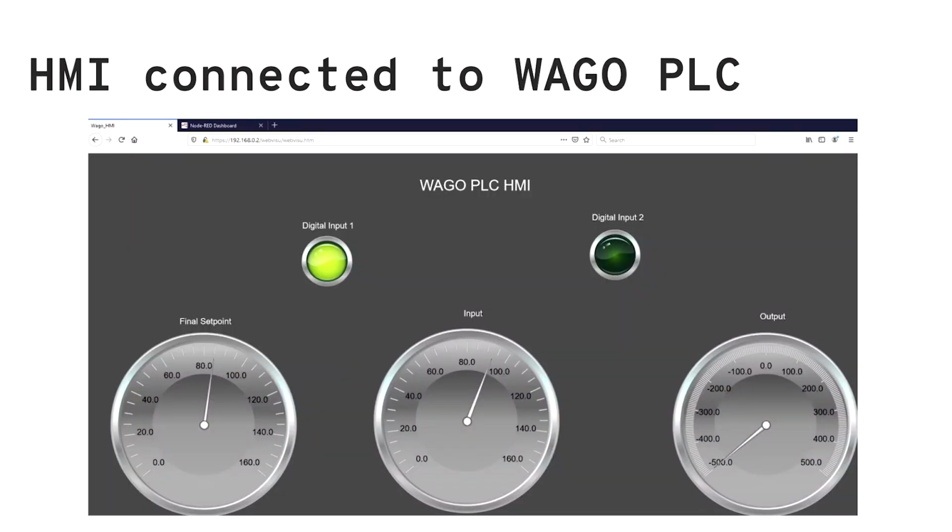And once you have your HMI, I have this example. The Wago PLC runs the HMI as a web service on the PLC itself. So to get the status of the PLC, you connect not through Modbus, but through a web server, the web service over HTTP in this case, to the PLC, and the PLC is running that HMI and gives back a visual output to the operator.